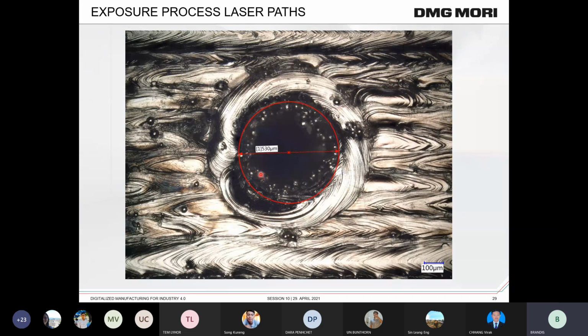Then the job preparation software controls the laser like this. So this is one melting process. And here we have the hatch line by line. You can see very easily that additive manufacturing for metal, at the end, is a welding process. So this picture looks like all other welding processes for metals.